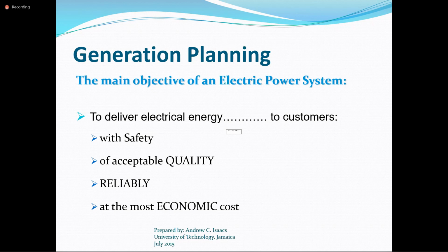But speaking of quality, if you have a stove whose timer is based on 50 hertz, and you plug it into a Jamaican system where the quality is not that good, meaning that the frequency is sometimes over 50 hertz, and sometimes under, then again, although you have the right equipment in terms of your timer, you're gonna have issues. So you may end up with the thing being too long, or you're taking it out too quickly.